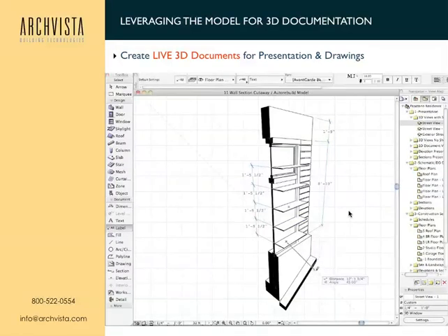And more importantly, this drawing is directly connected to my model. So while it looks like a 3D cutaway, well, it is a 3D cutaway, but while it looks like it's disconnected from the model, it's actually still connected. If I were to select one of the sunshades, they would select as an element, and if I move them, I would be editing the model, even though this is a cutaway. So this is a live auto rebuild view derived from the model.